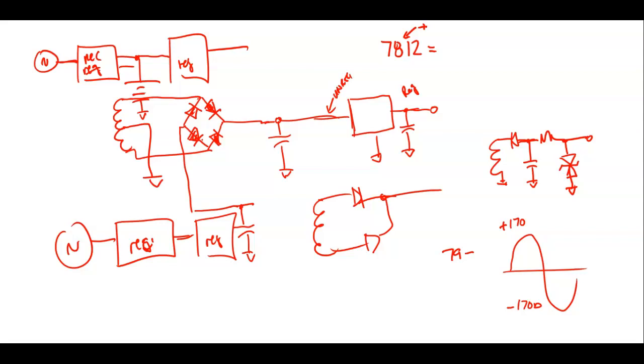About what voltage should you measure out of your alternator? What DC voltage should you measure when your car is running? About 14 volts. So your alternator regulates at about 14 volts. So 13.7, yeah, but it should be over 12 volts, guys, because it's got to charge the battery, right? Otherwise either your battery's got a short in it and isn't doing the filtering job, or your alternator's not putting out what it's supposed to. So you can check your alternator right off the bat.